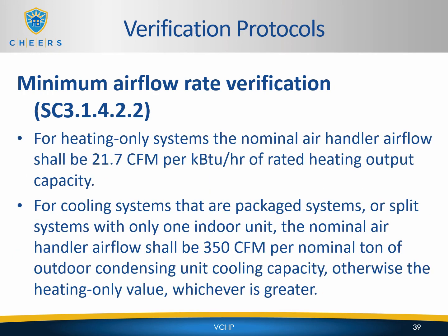For heating only systems, the nominal air handler airflow shall be 21.7 CFM per 1000 BTU per hour of rated heating output capacity. Again, this is a similar calculation or formula that we use. Typically, we'll use it on calculating airflow for duct leakage.